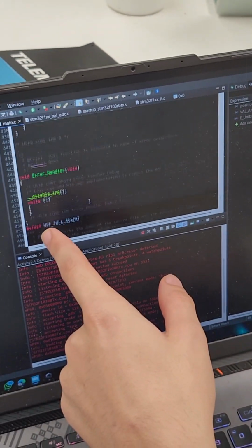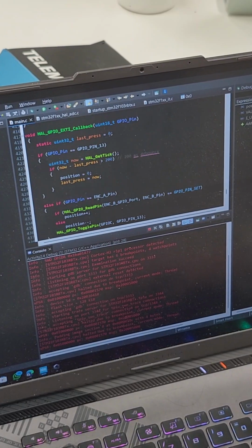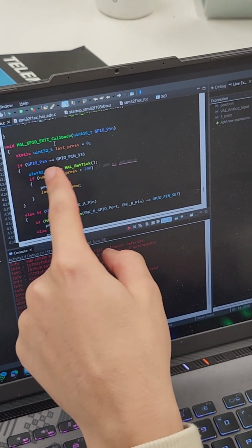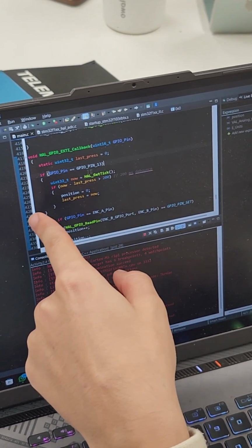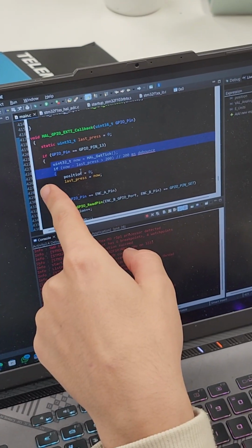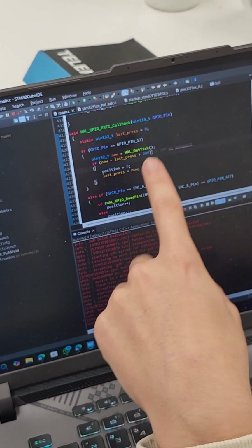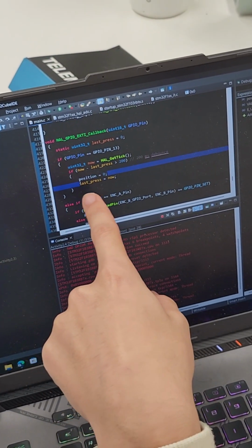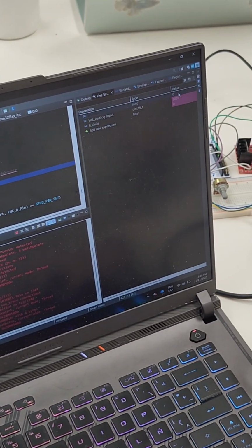with a small function insertion in the interrupt function, where we check which pin is the one that had the interrupt signal, and then we make a small debouncer without using delays, because we need to check on time, and then we change the value of position, and that resets the value to 0. And that's everything. Thank you.